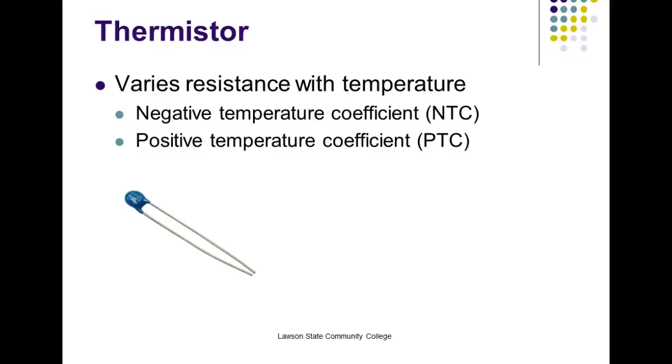And they can be designed different ways. If it's got what we call an NTC, that's a negative temperature coefficient. That means the opposition goes down as the temperature goes up. If we got a PTC type, then that means these are positive temperature coefficients. So that means as the temperature goes up, their resistance goes up. Probably the most popular one is this guy right here, I think.